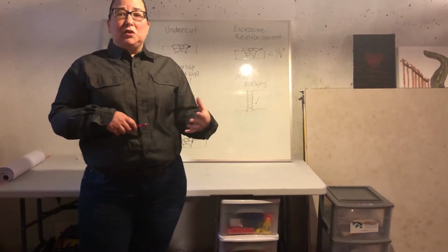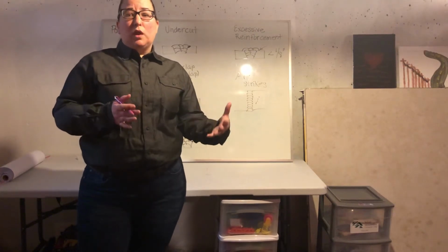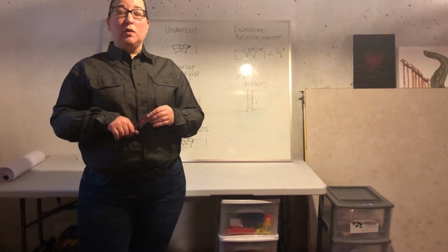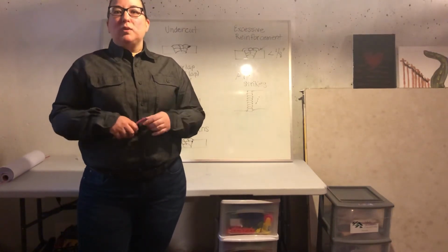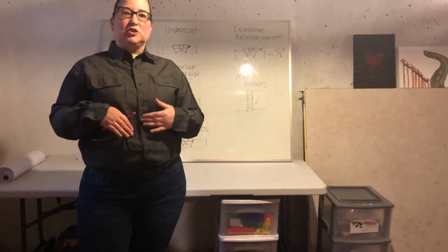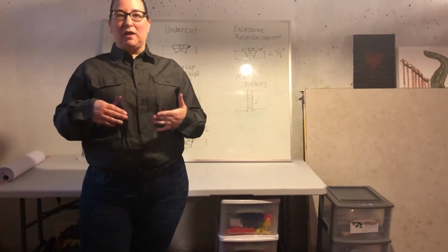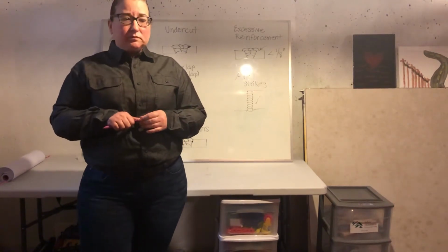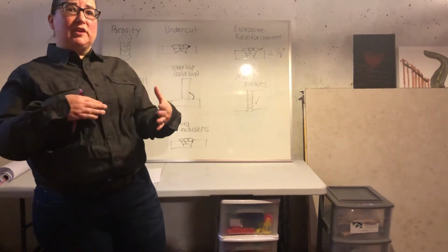For a less experienced welder, we're probably going to be on the lower end of that range because a hotter weld is tougher to control. For a more experienced welder, we might go on the higher end of the settings because we get that really great penetration and we're able to control the puddle through those years of experience and knowledge. So we really want to start at that point.